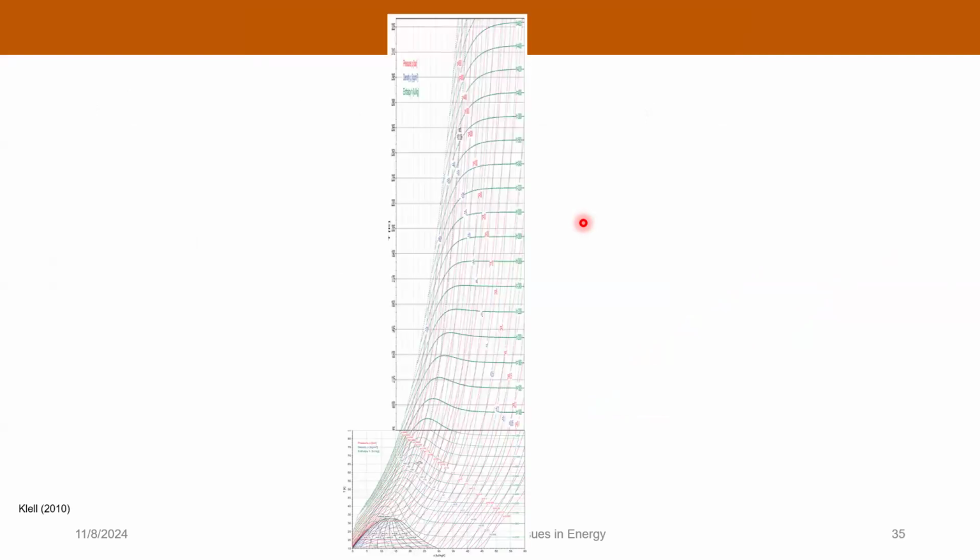Okay, it is much taller than the temperature entropy diagram for liquefied natural gas. And that's because the saturated liquid, the liquid vapor region down here is at very, very low temperatures. I can't even read that. The numbers are so small, but yeah, it's like 30, 35 Kelvin. So you're like minus 200 something degrees Celsius.